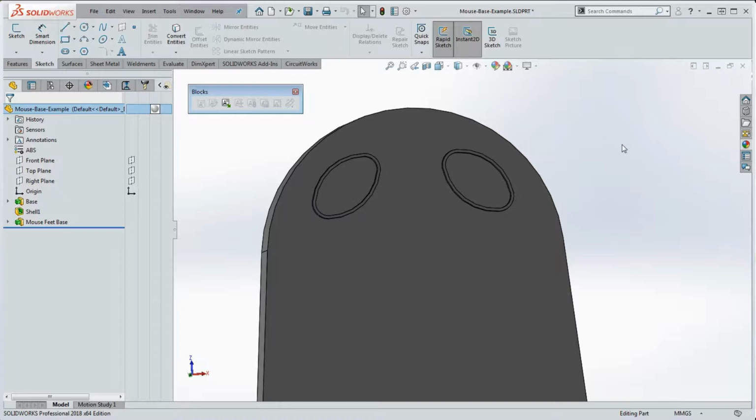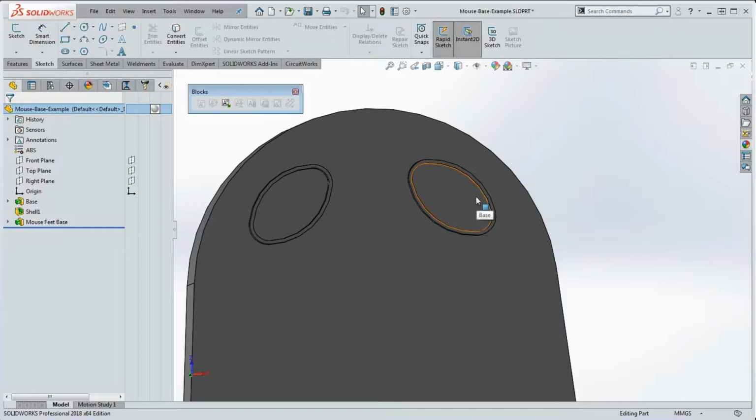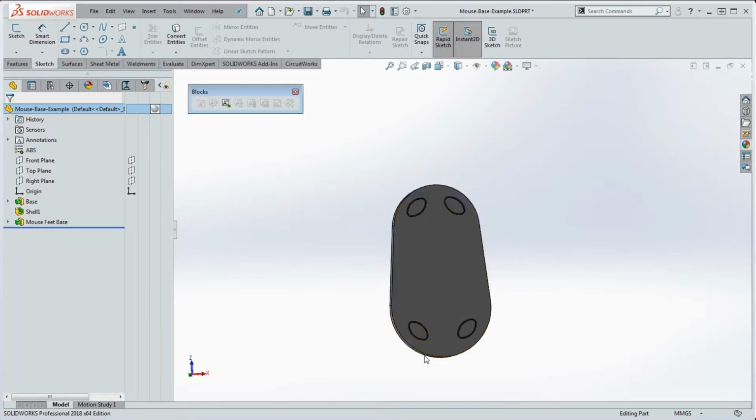So he was having difficulty with it, and I think a solution to that is to create a block in order to define this a little bit better, and take that block as a loose sketch element in there, and define it with distance relationships, like dimensions, and with an angular dimension in here too, in order to define that both on the top and the bottom. Of course, if you split this in half, you can take whatever you sketched on one side and mirror it to the other side. So let me show you how that was put together.